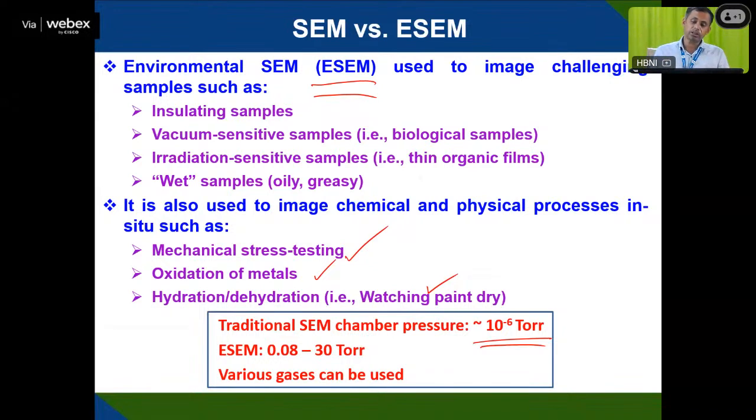Especially, the scanning electron microscope mainly gives information about four things. One is topographic information, one is shape and size, the morphology, and then you are able to get crystal information. As well as composition analysis, whether what type of particular element is present and how much it constitutes, atom percent, all that information you will be able to get by using the scanning electron microscope.